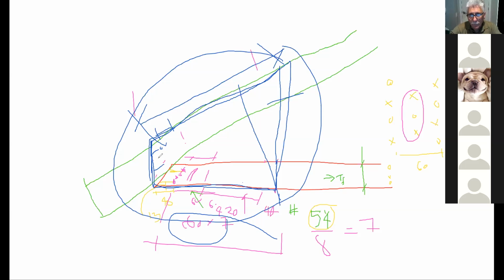So all we need to do is specify the bottom length, or that longer length, right? Because from this bottom length, the carpenter will be able to calculate what this length is here, and then this length is going to end up being automatic. It's like I said, the carpenters all work with their squares. You understand? With this ratio of 12 to 4, they know what this angle is with their square. You follow? So he'll be able to work all of that out.